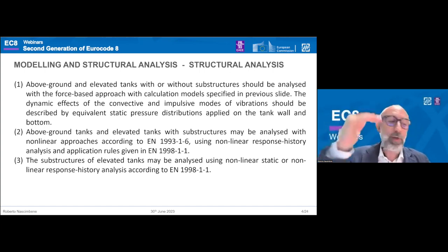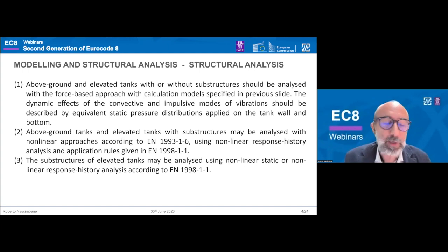We move from modeling to analysis. Above ground and elevated tank with or without substructure should be analyzed with the force-based approach using the calculation models specified in the previous slide according to the equivalent mechanical model.